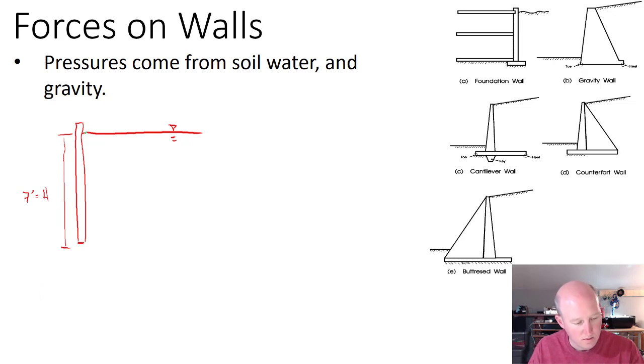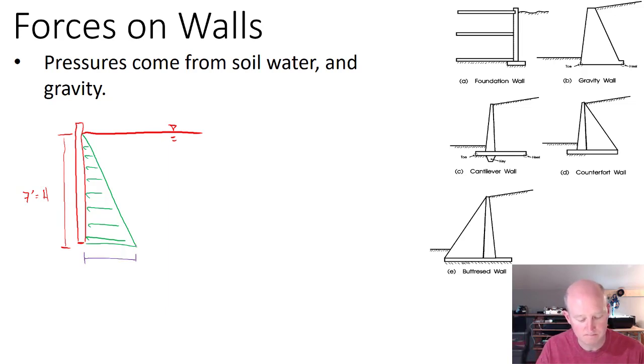So in fluids, we probably drew a triangular pressure distribution and described the force of the water this way. And if we wanted to know what is the pressure at any point, but in this case particularly at the bottom, P would be, the pressure would be gamma times H. And so for water, gamma is the unit weight, and for water that's 62.4 pounds per cubic foot.